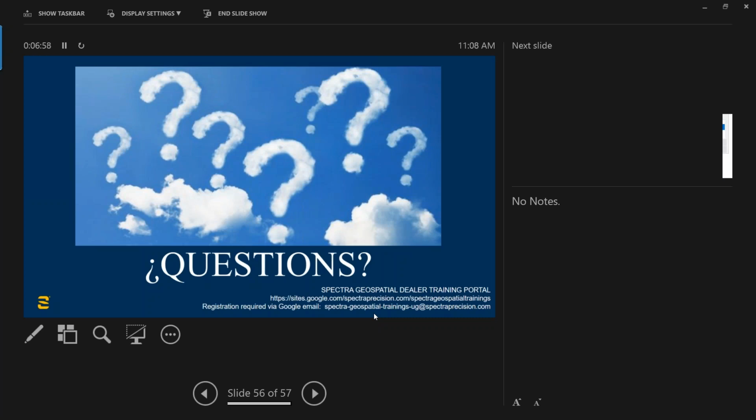But I think most people, they go out and they've got one skanky benchmark over here and another one over there, and they're only a couple hundred meters apart, and they think, hey, more is better. But in many cases, you're actually introducing more tilt from your measurement error than the actual physical effect that you're trying to solve. So keep in mind that geoid models already have this tilt baked in, right?